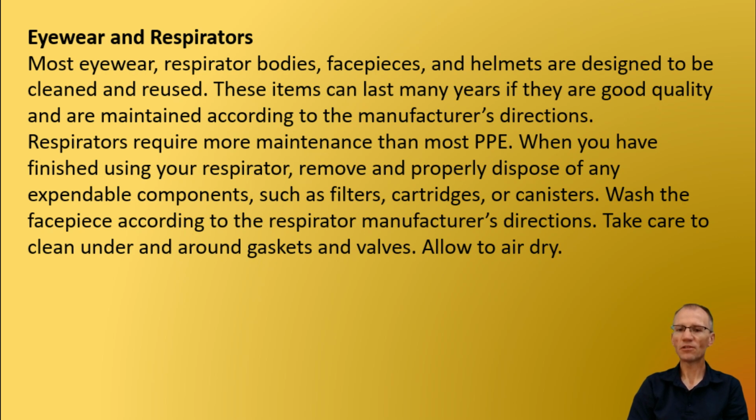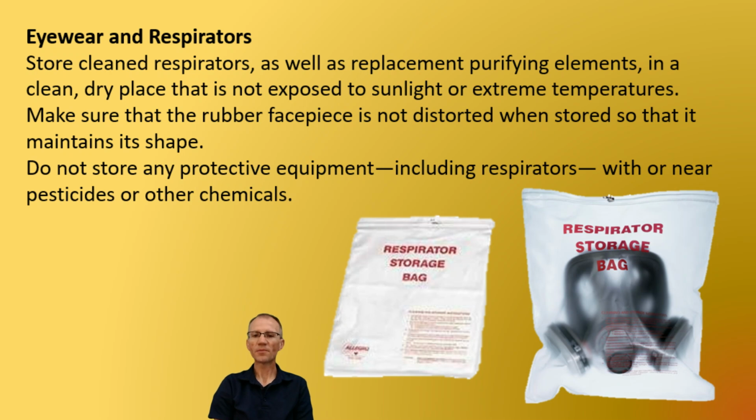When you have finished using your respirator, remove and properly dispose of any expendable components, such as filters, cartridges, or canisters. Wash the face piece according to the respirator manufacturer's directions. Take care to clean under and around gaskets and valves. Allow to air dry.